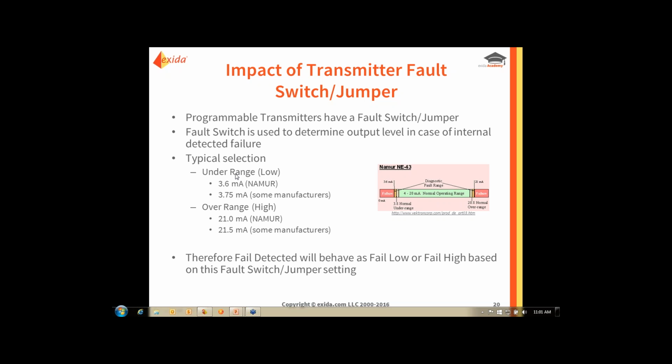You want to make sure that the system is not messed with, and that the deviation alarms are clear and well annunciated. So we typically suggest to put it in the safety instrumented system, just because that's better controlled. But I can't say that the standard absolutely requires that.